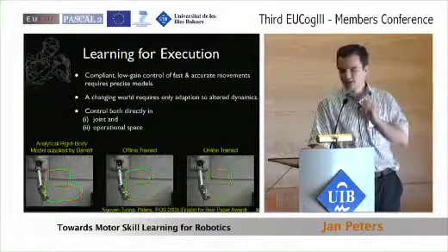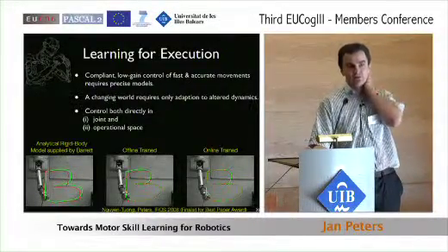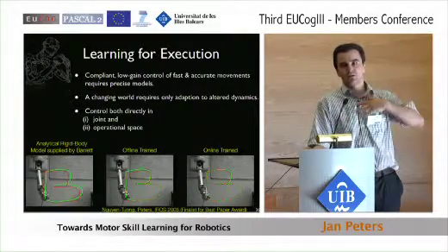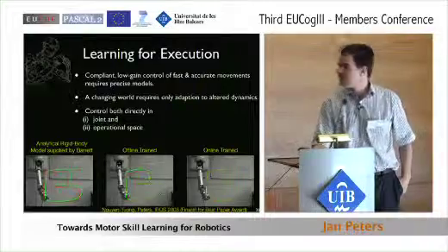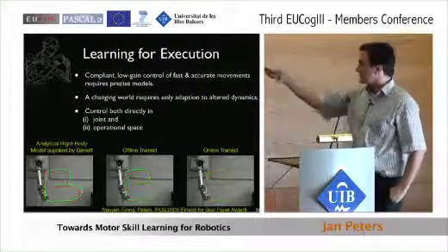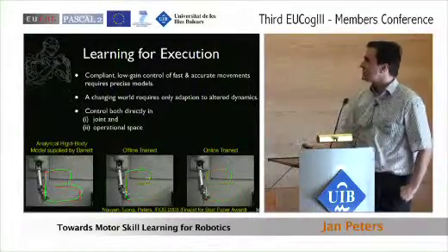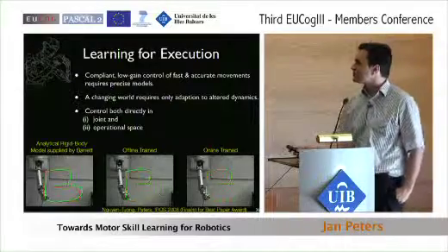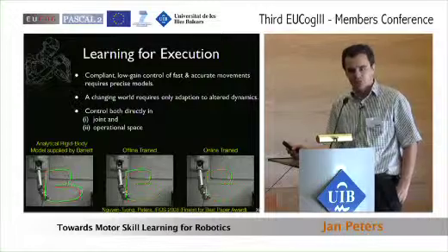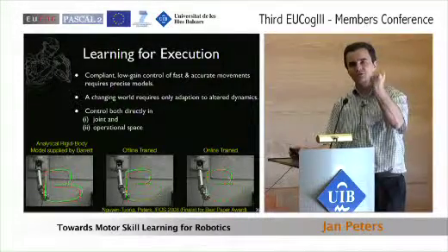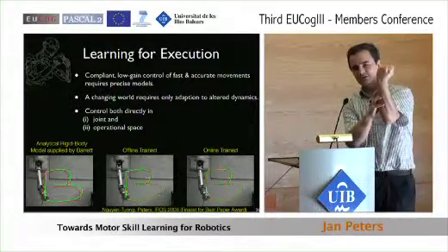how we can control accurately, and for that we need to update our model, or more precisely, use machine learning methods in order to learn better models. And what you see here on the left is the best model which the manufacturer of our robot could provide if you put it in a low-gain mode, while the manufacturer, of course, runs this when the robot is in constant co-contraction, so he's constantly stiffening its muscles,